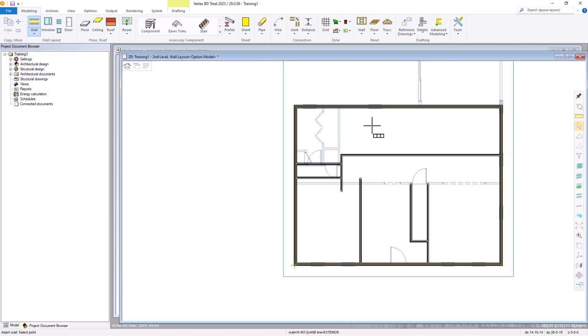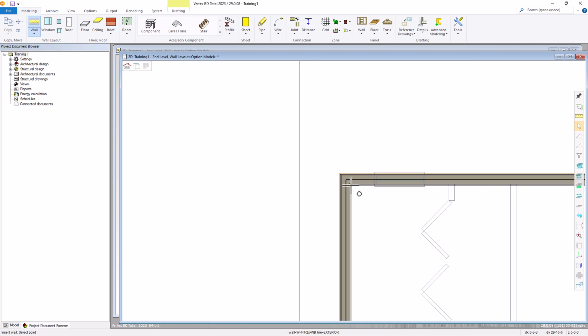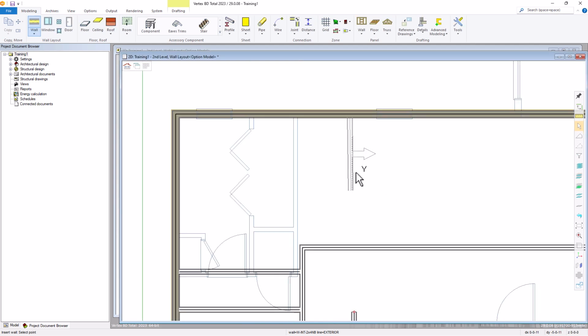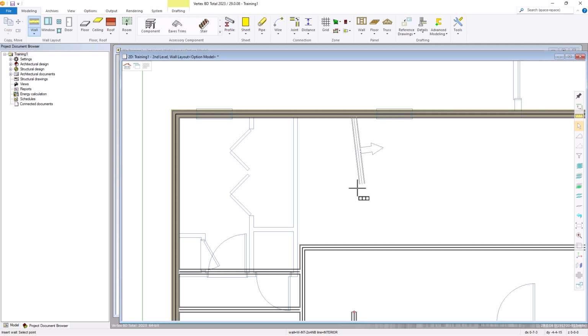Next, we have some walls in this area. We have another wall that is 12 foot 1.5 from the exterior wall. Go to this corner. Q, the letter U. Again, 12 foot 1.5. And this wall, I'm coming down at it from the top down. I need to change the offset. Flip that around and butt that one up against this wall. V to confirm.